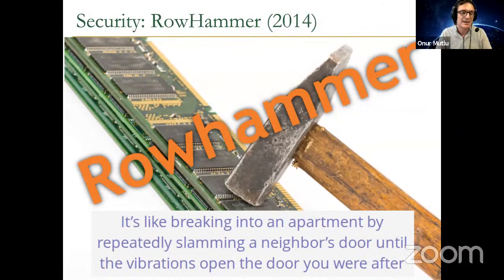It's essentially about disturbance. Whenever you're hammering one row, you're actually causing disturbance to the cells around that row, because these cells are too close physically. And also these cells are too small physically. As a result, they're vulnerable to the disturbance noise that's created by the hammering of these word lines. And your hammering means changing the voltage repeatedly many, many times on this word line, right? So this is going to become a bigger problem.